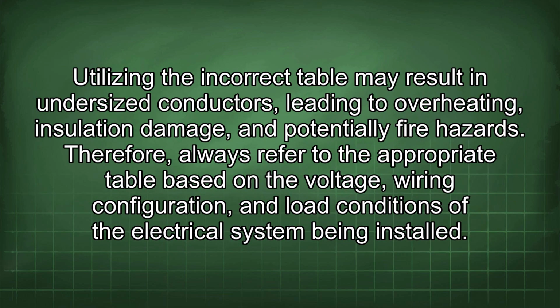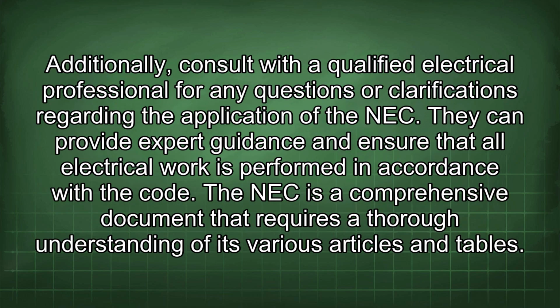Utilizing the incorrect table may result in undersized conductors, leading to overheating, insulation damage, and potentially fire hazards. Therefore, always refer to the appropriate table based on the voltage, wiring configuration, and load conditions of the electrical system being installed. Additionally, consult with a qualified electrical professional for any questions or clarifications regarding the application of the NEC. They can provide expert guidance and ensure that all electrical work is performed in accordance with the code.